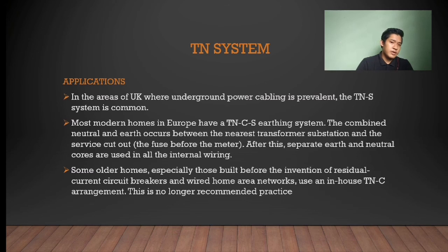The application of the TN system. In the areas of the UK where underground power cabling is prevalent, the TN-S system is common. Most modern homes in Europe have a TN-C-S earthing system. The combined neutral and earth occurs between the nearest transformer substation and the service cutout, the fuse before the meter.